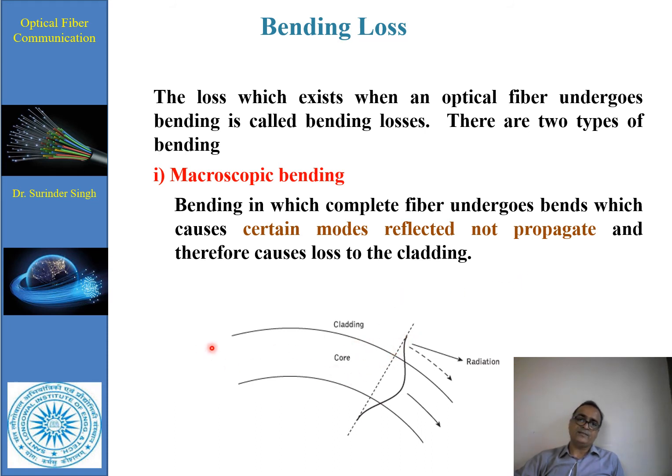The energy basically propagates in the optical core of the fiber. Part of the energy is also propagating in the cladding, as given by the mode field diameter. And at the bend, the outer part has to move at a faster velocity, and the inner part has to move at a slower velocity in order to travel along with the optical fiber.